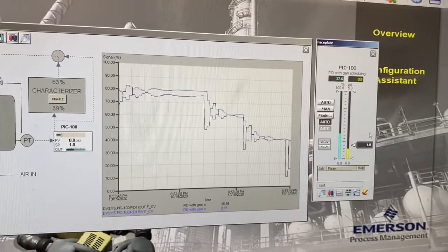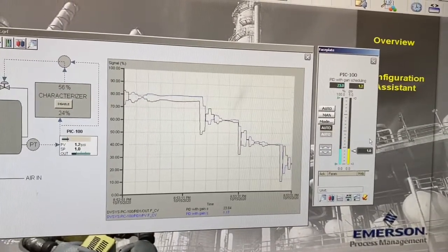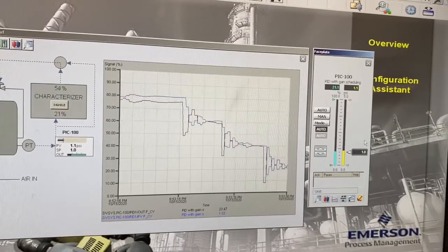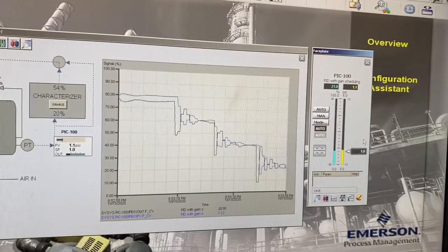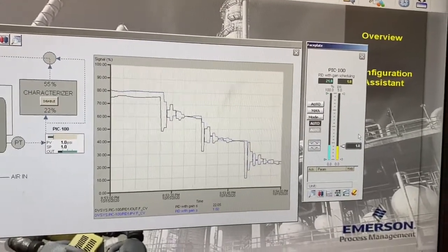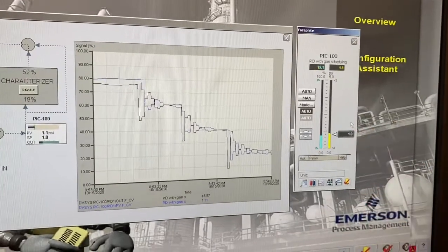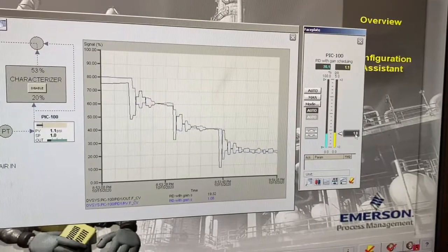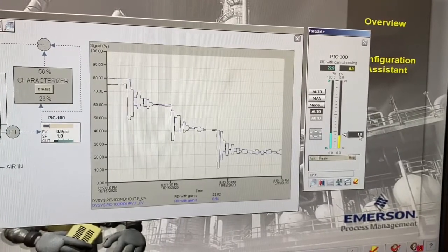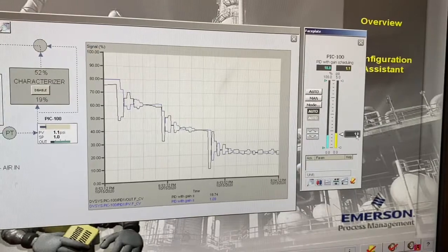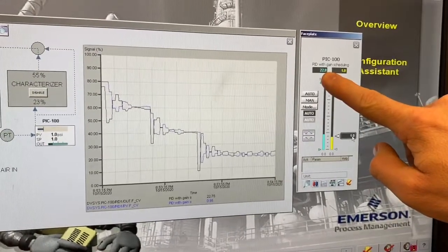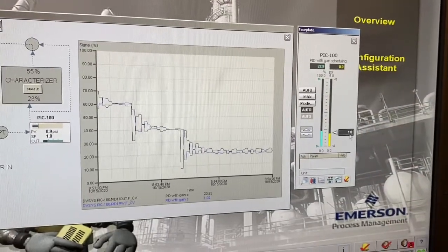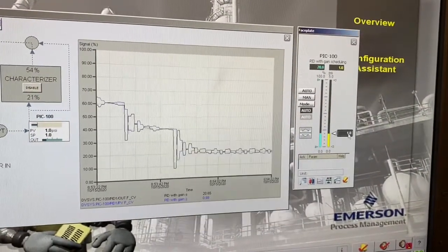And this zone here was where we started to get, see how it does. Well, it's starting to stabilize, it looks like. We're right around 1, so this is where it was quite sluggish before. But it does look like our controller output here is oscillating. So we might have to lower our gain a little bit, but let's go back up to 2.